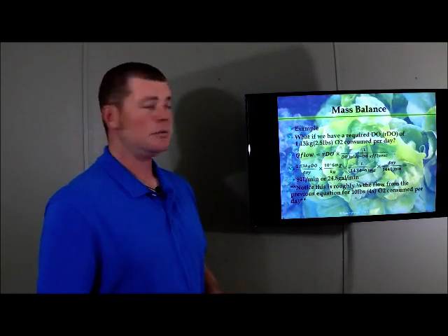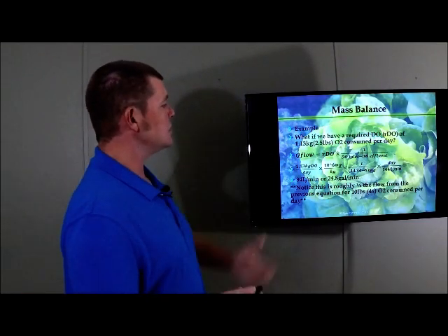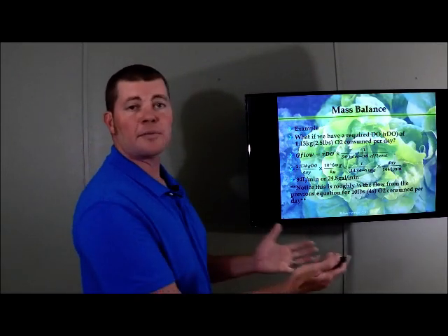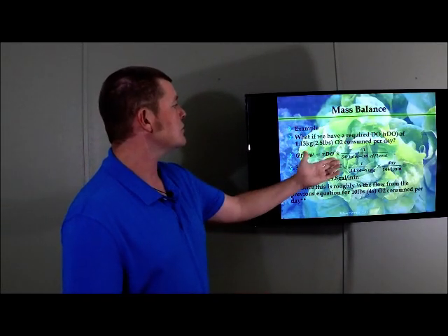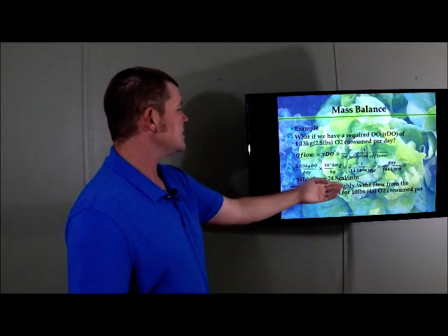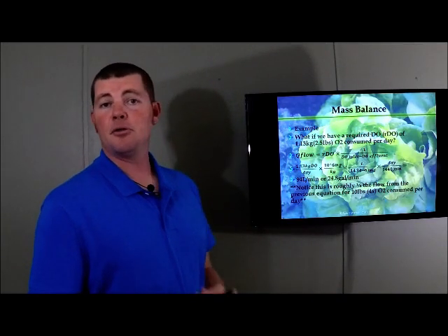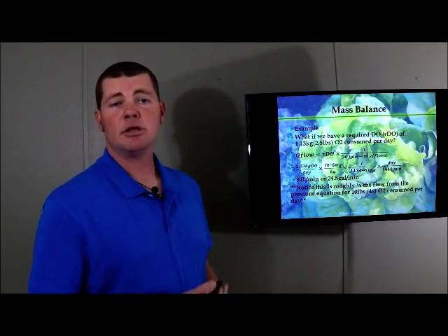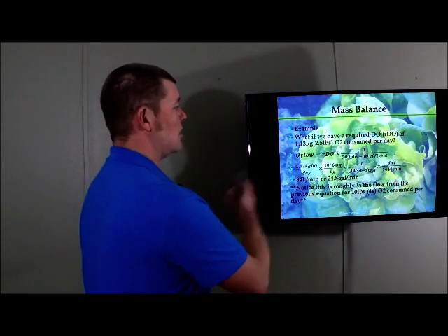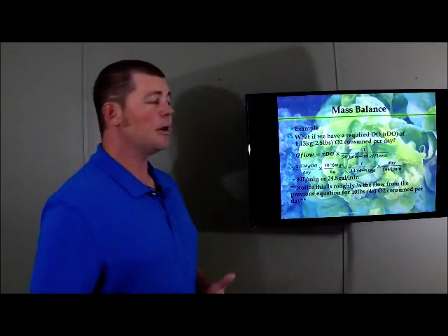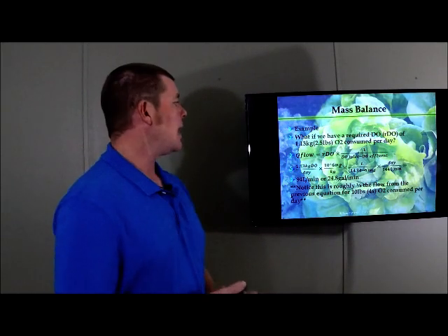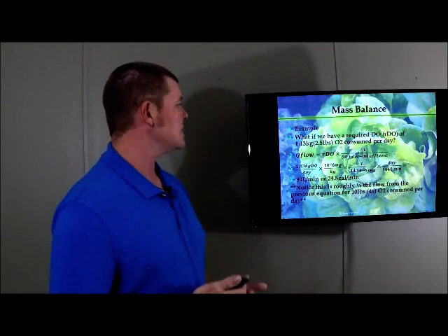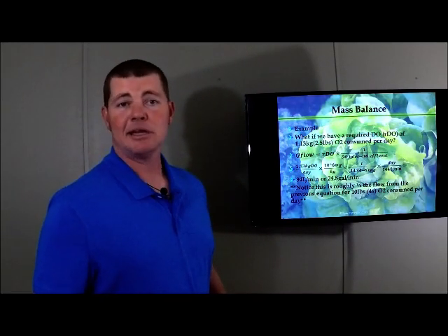You can see how these equations actually work together. If you do a few, do them with both equations, and you'll see you can work from either way. If you know the dissolved oxygen requirement, you can use this to calculate the flow rate. If you know the flow rate and the oxygen, you can use that to calculate the dissolved oxygen requirements. So both of these work very well, and they're formulas that you need to know to calculate needed flow rates.